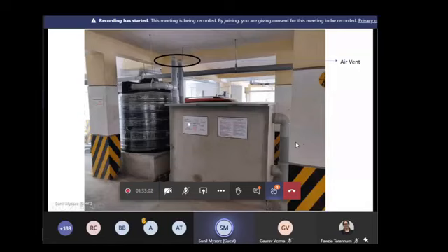Even if you don't use it, it's not a big problem, but it is recommended that you use it because there's a lot of silt. Sometimes the roof doesn't get maintained very well, and you have a lot of silt coming from the roof. That can all get trapped in the sedimentation tank. As a good practice, it's better to use this. And the water is not wasted, mind you, it is still harvested. It's just that you're not using it for primary purposes, you're just using it for secondary purposes.